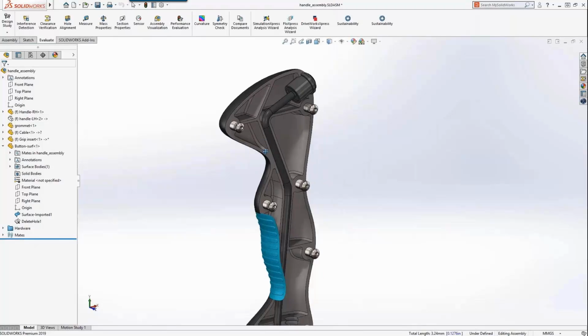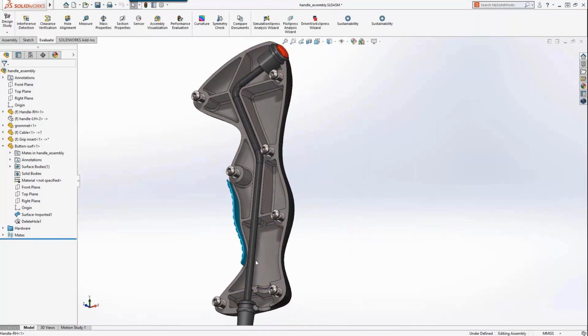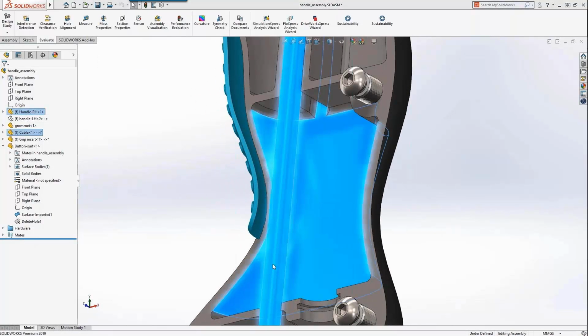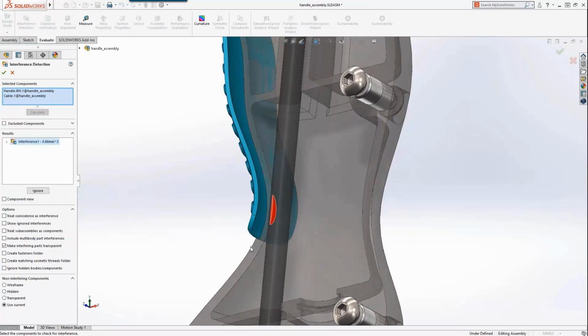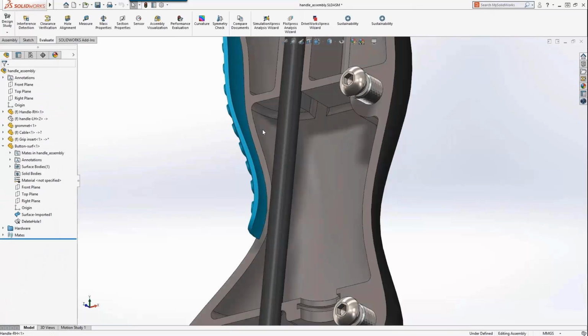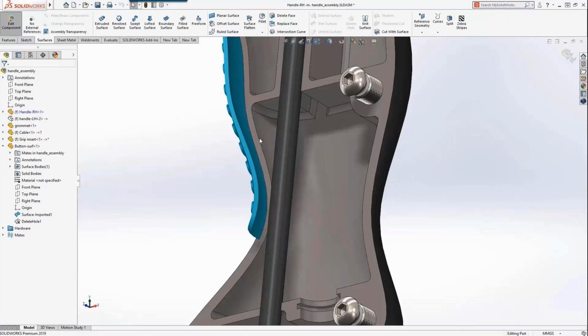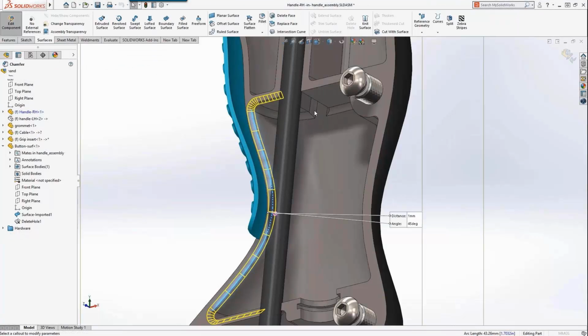Previously, these holes could be removed by selecting the edges of the holes and hitting the delete key, but this method was not easily discoverable. Now in SOLIDWORKS 2019, a delete hole button is available, as well as in the property manager for editing. The holes are removed and the surfaces are now watertight.